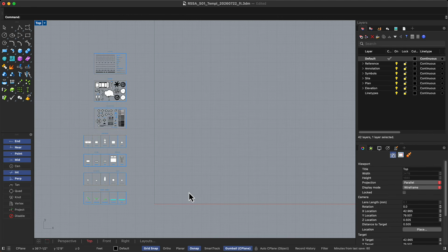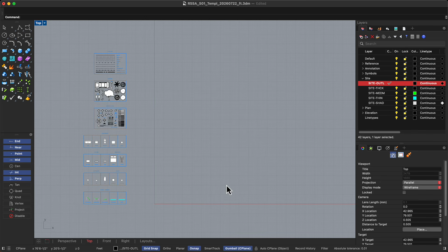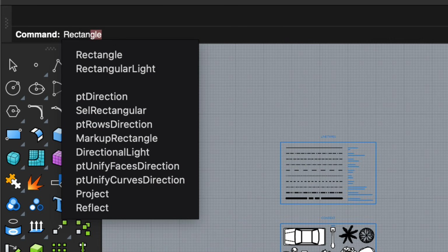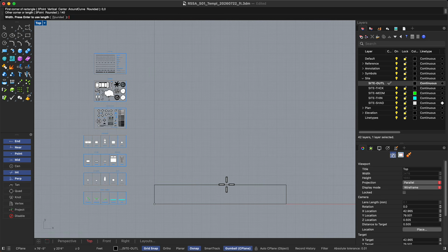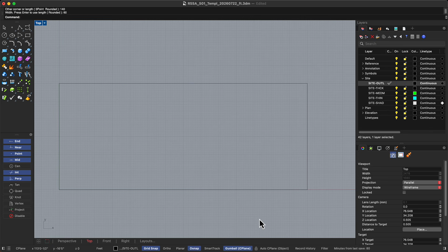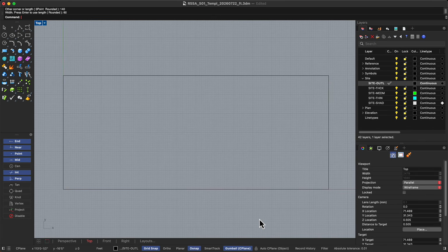First off, open the series template. We're going to start by drawing the lot's property line, and let's be precise about where it lands. Make the heaviest site layer active, the template's site outline layer. Our lot is a simple rectangle, so we'll draw it with the rectangle command. For the first corner, don't just click somewhere on the screen. Type 0, 0 and press enter. Then, for the opposite corner, type the lot dimensions directly, 140 feet by 60 feet, and press enter. That anchors one corner of the lot on the origin, and that point becomes our datum.